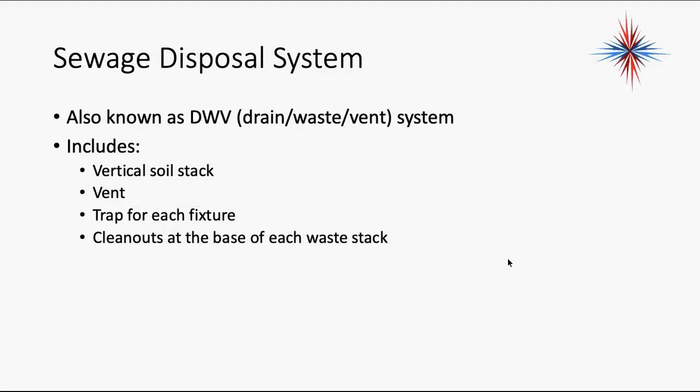Sewer disposal systems are also known as drain, waste, and vent systems. Okay, DWV, our plumbing program has 2 entire courses on this, DWV1, DWV2. Okay, it includes a vertical stack, has a vent, has a trap for each fixture, and has a cleanout at the base of each stack.